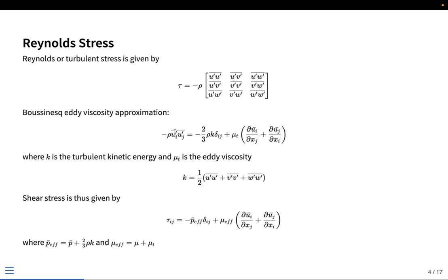So what this eventually turns out to is, if you have the normal fluid, as I said before, this gives us an estimate of the fluctuation quantities which we do not have directly. So we measure u bar. Since we do not know the exact value of u prime, what we can measure is the statistics of these fluctuations. Since these are completely random, the mean quantity of u prime will turn out to be 0, because the entire mean of the velocity is captured in u bar and whatever is left out will be 0.